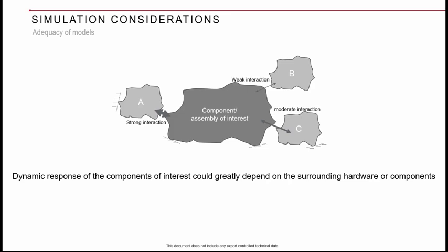But with the bracket present, the mode shapes can be different again. So that is where we should be taking a call. So it is always suggested to perform the analysis with all these components considered, and later you simplify if you find that they are not contributing to the response of your component of interest. It is good to consider them so that you can make proposals to the test plan also, so that the testing is also representative of actual reality.